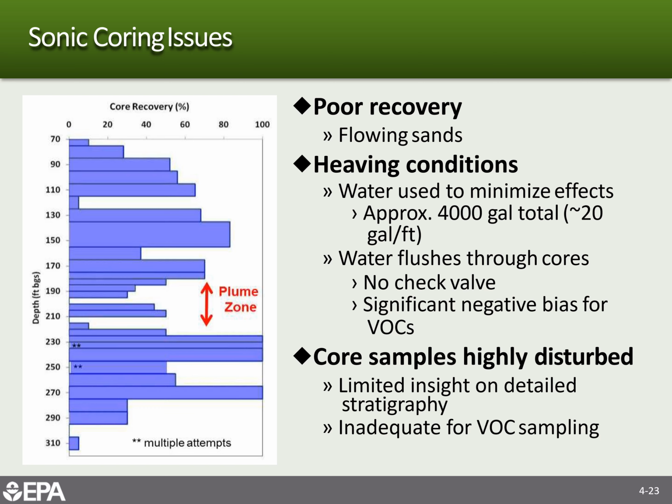If the formations are too dry, then you have to use some water in order to advance the tools and keep things from sticking, and that can dilute any of the fluids in the core, and you'll get reduced concentrations for any VOC samples that you collect. And it can be highly disturbed.